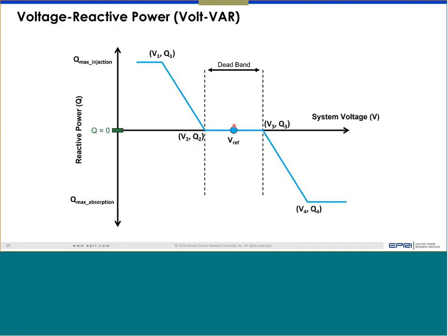In this curve there could be a lot of shapes possible, but the common one people discuss is that you will have a target voltage, say nominal voltage, 1 pu. Or you have a program where you want to maintain 0.98 voltage. Whatever your target voltage, that should be your VREF. Now around the VREF, there might be plus or minus 1%, 2%, or 3% where you don't mind if the voltage varies. You say normally voltage always varies up to 3%, so I don't care.